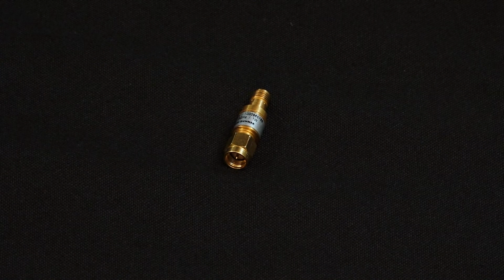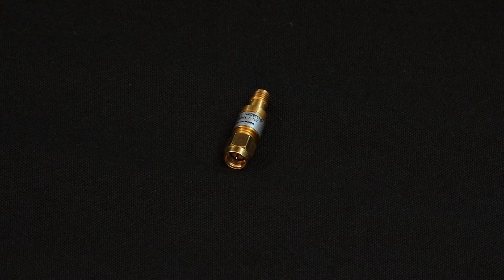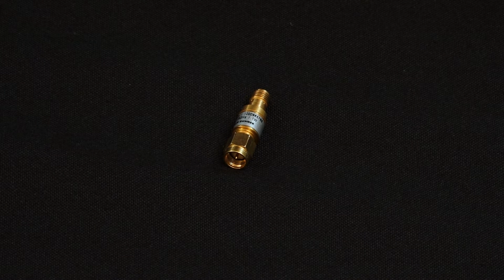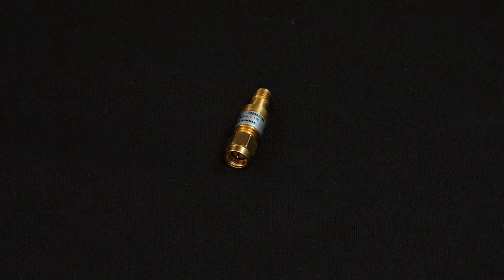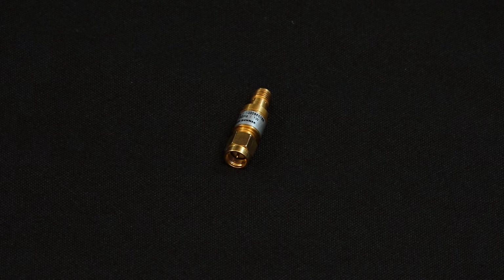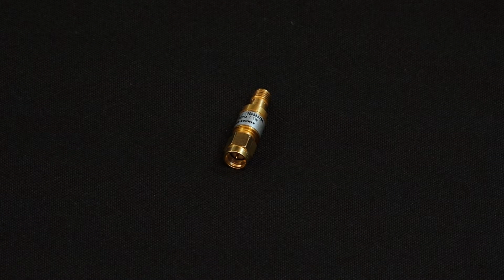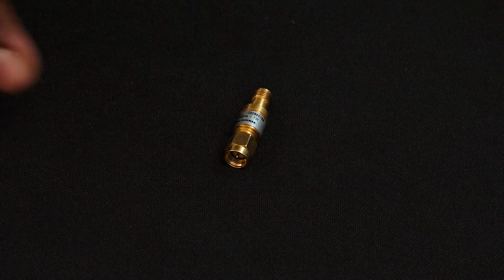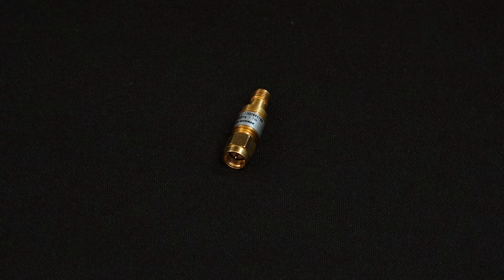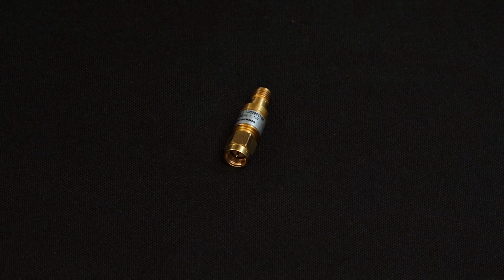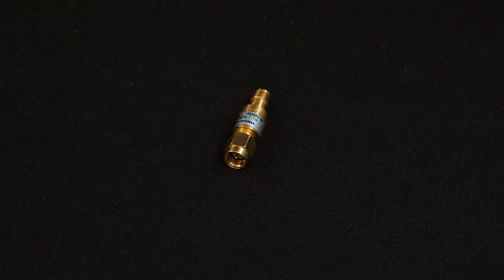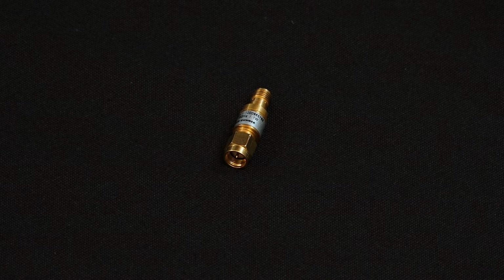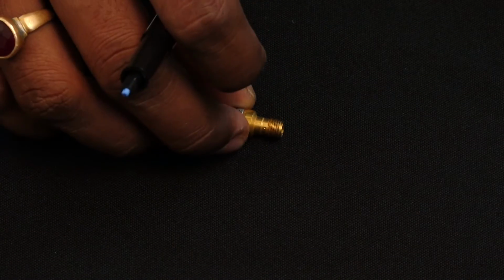These attenuators are passive components, so they don't consume any power of their own, and their ratings are in decibels. They are dependent upon the power of the signal and the power output through the attenuator. That's why it's in decibels, and I'll talk more about how these attenuators impact the whole calibration setup when I talk about the calibration in more detail. However, as I said, you have to take care of these attenuators during the calibration processes because they directly impact the measurement that you're going to do. The attenuators that we use generally have a rating of 10 decibel or 20 decibel. However, attenuators with a higher or lower decibel rating are also available, and it's a matter of preference as well, or the signal that you're applying. So this is the fifth component, attenuator.